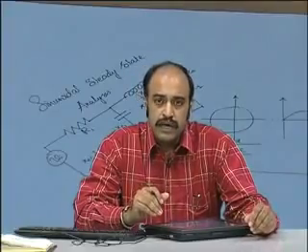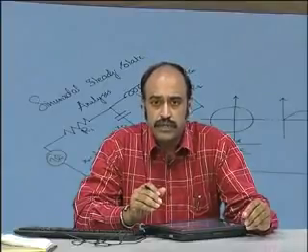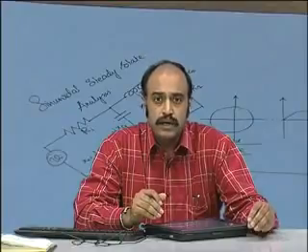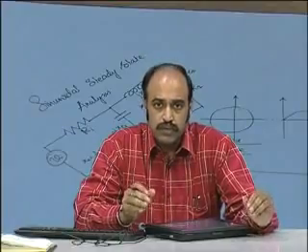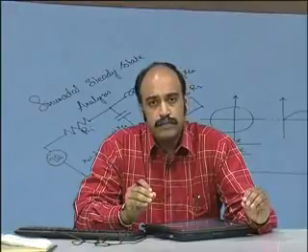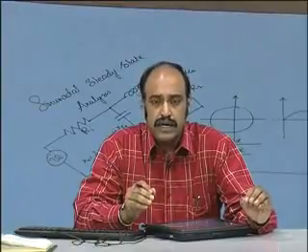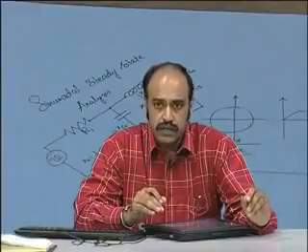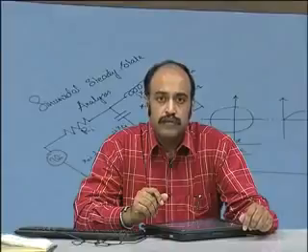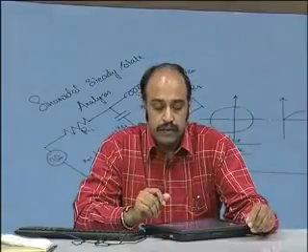So, for a sinusoidal input signal, because most of the components that you will be using in the circuits are linear, you will see that all the branch currents and node voltages will be sinusoidal. However, there will be phase shifts with respect to the input voltage that you will be applying.